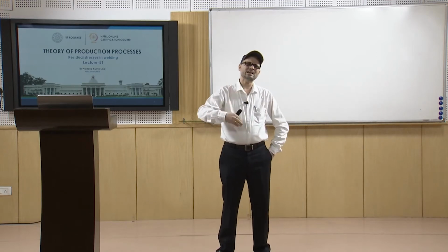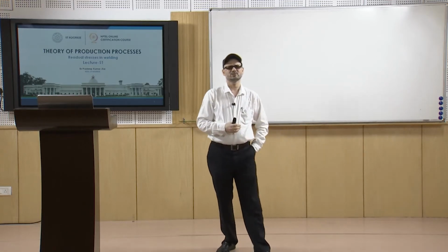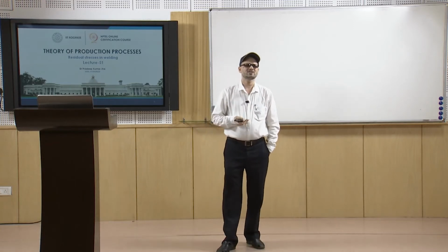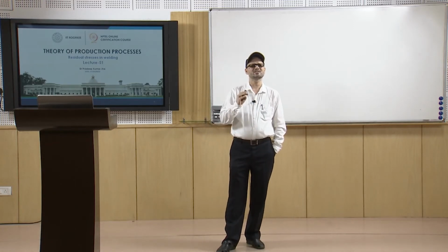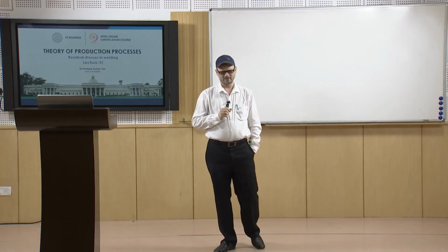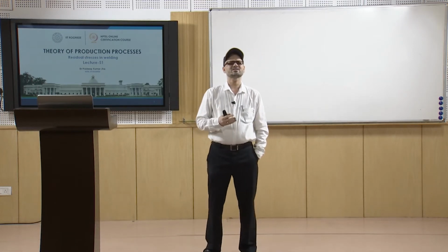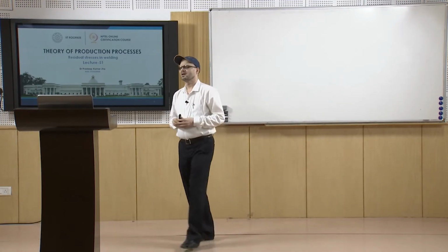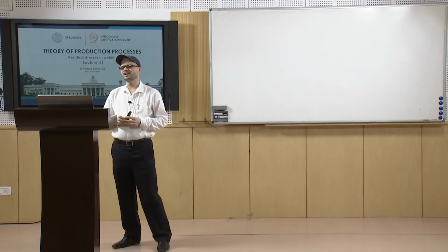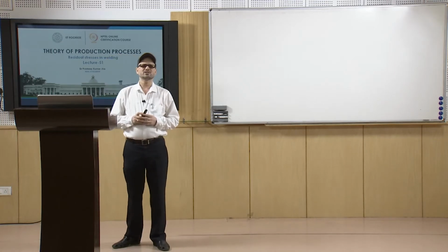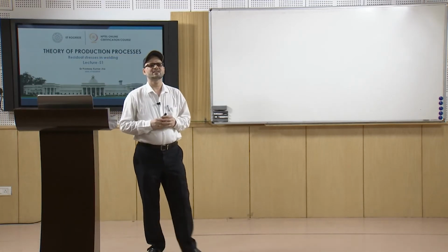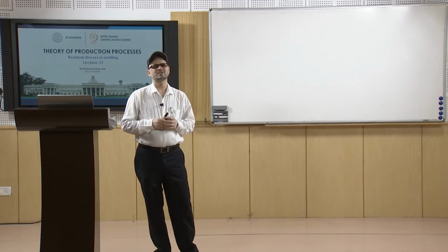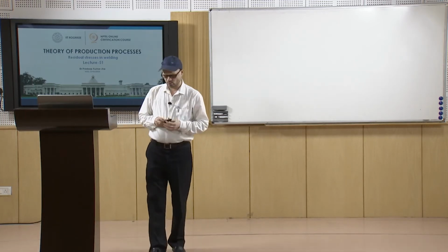As we have supplied energy into the body, the presence of residual stresses represents storage of energy within the body, and they are elastic in nature. Being elastic in nature, they can be released by operations which release the elastic deformations with consequent dissipation of elastic potential energy stored in the material.